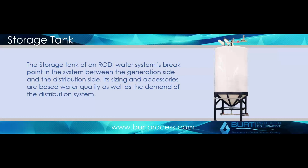And actually, when you get to very high water qualities, you generally want this tank to be very, very low as far as an actual volume is concerned. These tanks do tend to be thermoplastic in different applications, such as pharma. They can also be a polished stainless steel, and they are generally sealed off to the atmosphere.